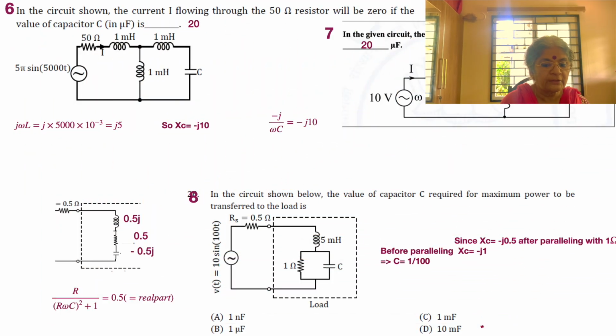We have what is called a situation wherein 0.5 ohm plus J0.5 ohm, that is the resistor and the inductor at the beginning of the circuit, should be supplemented by a pair of elements. First is, of course, the same old resistance 0.5, and then the complex conjugate of the imaginary portion of the impedance, that is 0.5J.